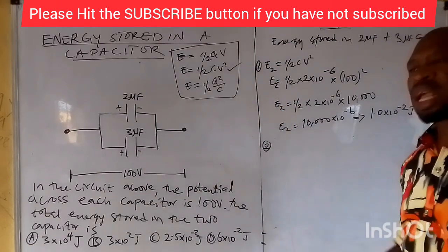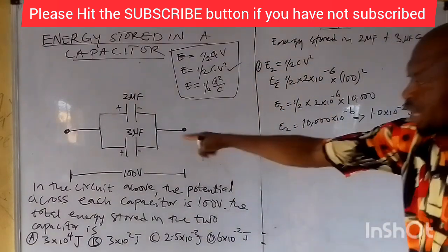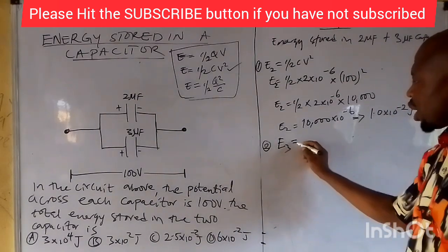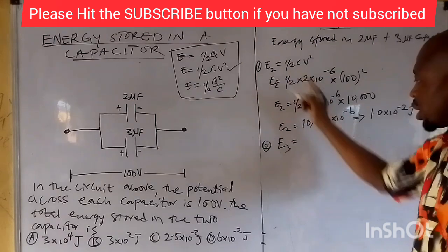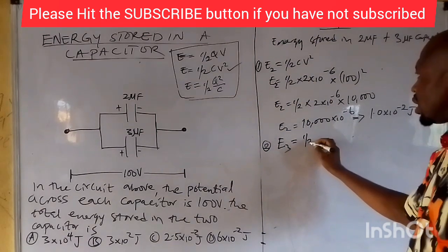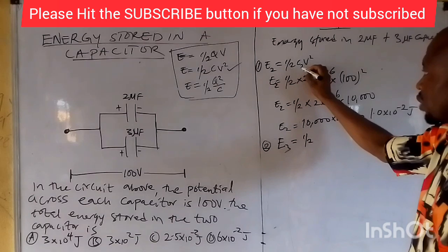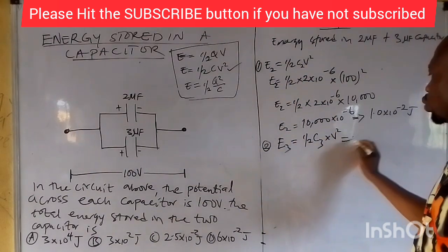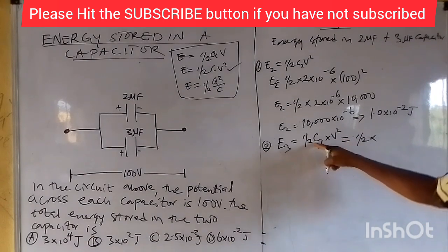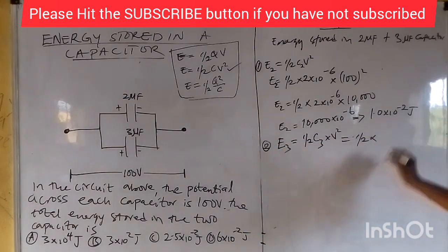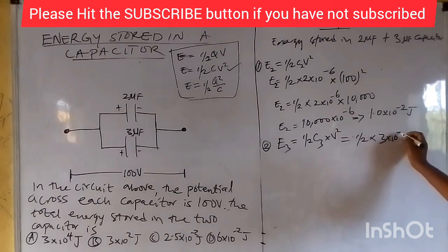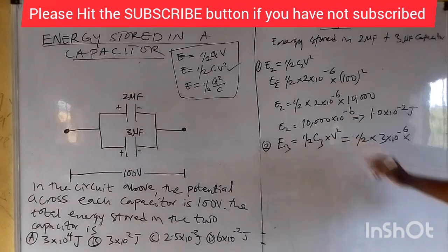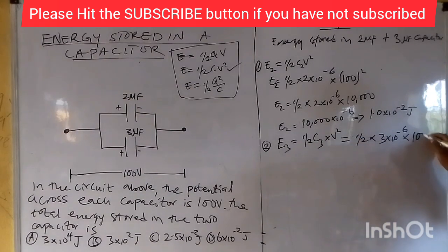Now second stage, energy stored in the 3 microfarad capacitor will give us E3. E3 is the same formula, half C3 times V squared, which will give us half times C3, which is 3 microfarad, 3 times 10 raised to the power minus 6, times that of V. V is 100.